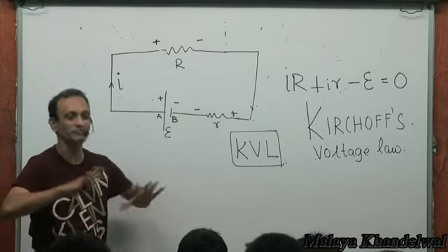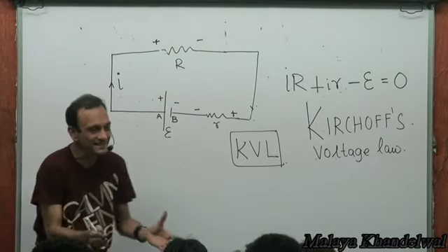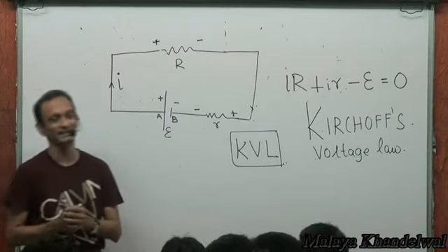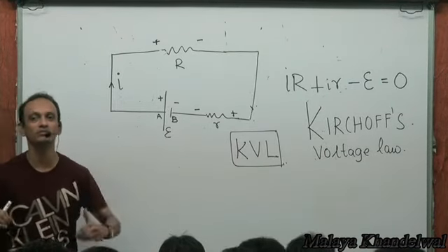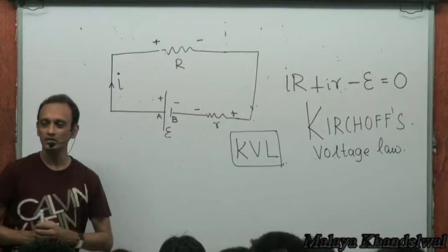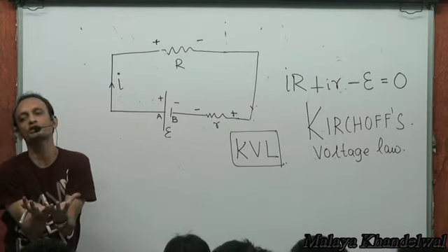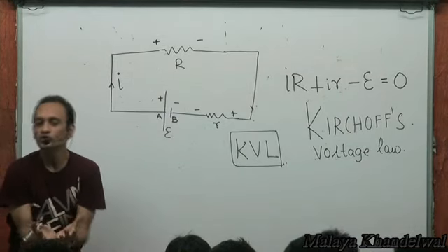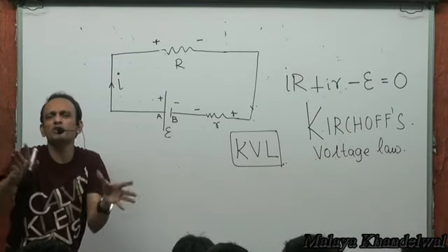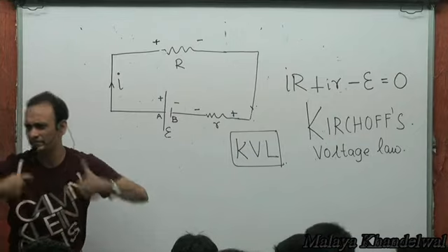Let's build it up. I'm going to look at all those variations. Let's go from scratch and build it up, right? Let's not jump to things right away. So that's Kirchhoff's voltage law. The algebraic sum of the potential drops in a closed loop is going to be 0. So we'll take drops: all drops positive, all increases negative, right?